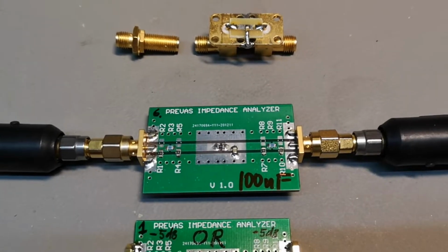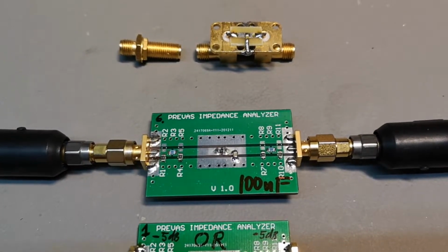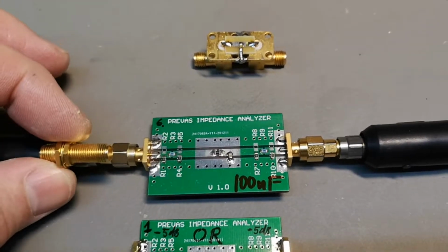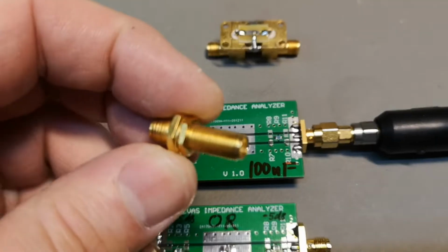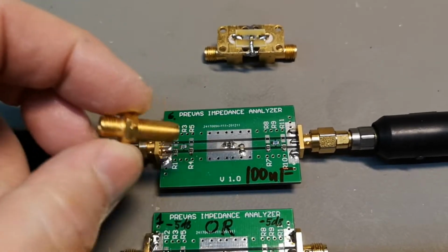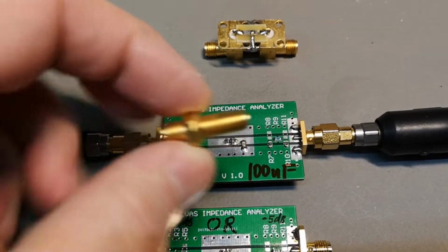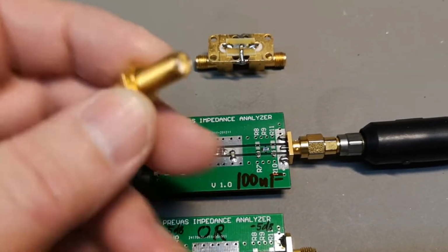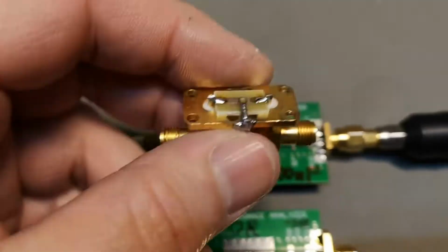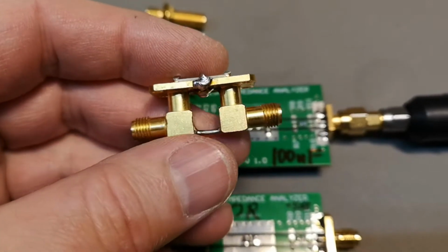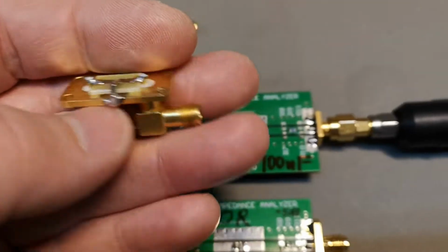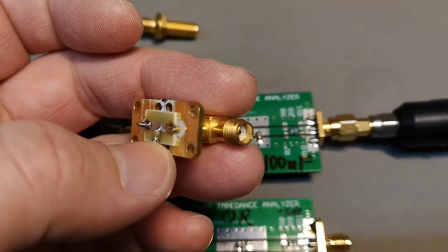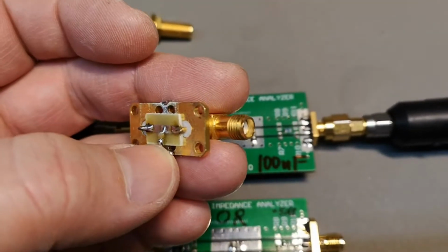So here is what people normally do. They normally just zero the analyzer with a through connection like this, so that the input and output are connected together, and then they put in their tester. It could have been other connectors like the through connectors, and then here is a little 100 nanofarad capacitor.